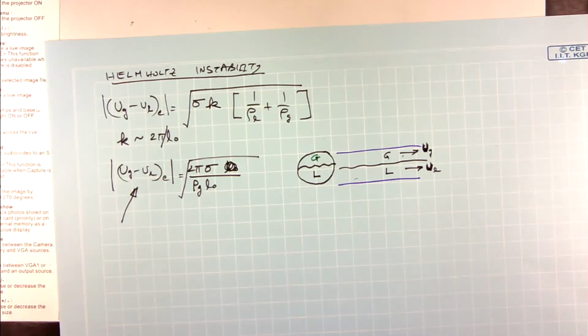So, as I mentioned, depending on your configuration, you can get different types of flow regimes. With the same mass flow rate and everything else, if I convert the horizontal pipe to a vertical pipe, whether you have an upward flow or a downward flow, things will start changing. Okay. So, now let us look at the simplest configuration, that is a vertical pipe with an upward flow, because you do not have the asymmetry.